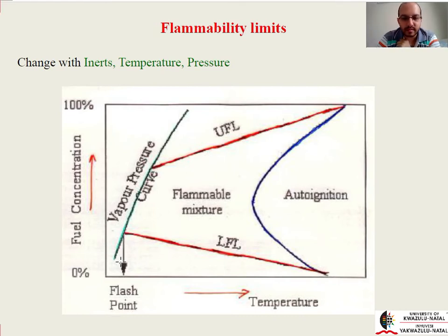So, as we increase temperature, the range of flammability increases. And the reason why we have this flammability range is because this is the region where the ratio between your fuel and your oxygen is actually good enough for all of that fuel to burn. Okay?